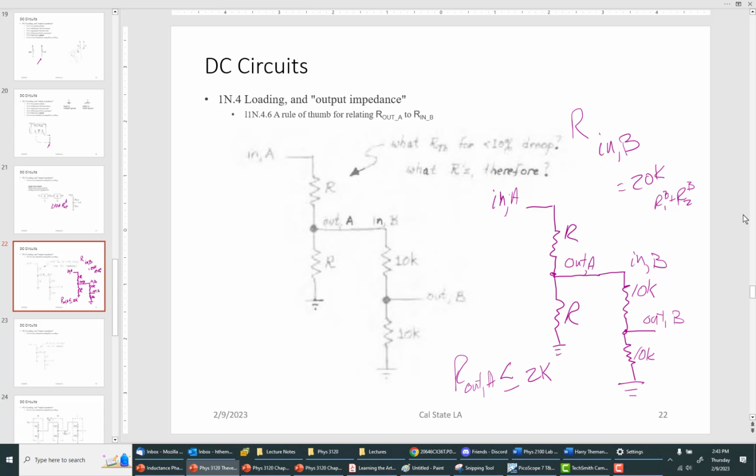Because we don't want anybody to be worried, because you're going to say to yourself, well, if I have a load attached to B, don't I care about that load? And I'm telling you right now, you don't. There's nothing attached to B. So B represents to A a load going through the two resistors into ground, right? You see that? Because it's a pathway for current.